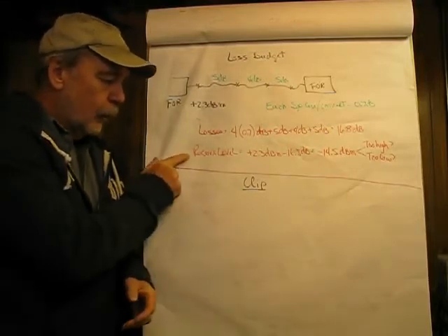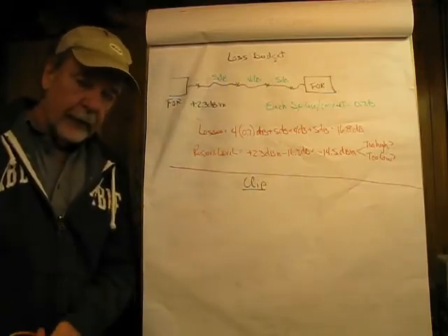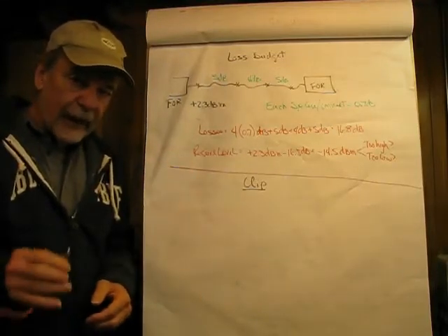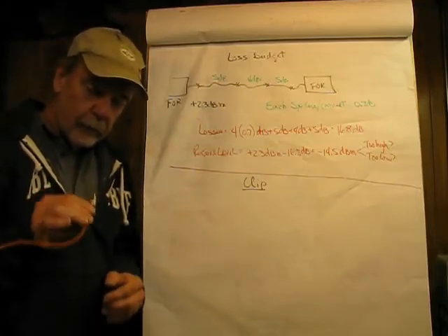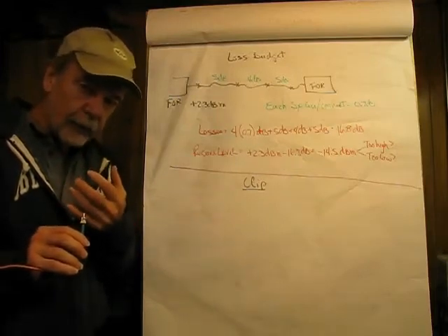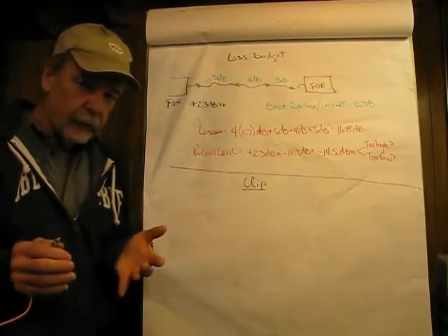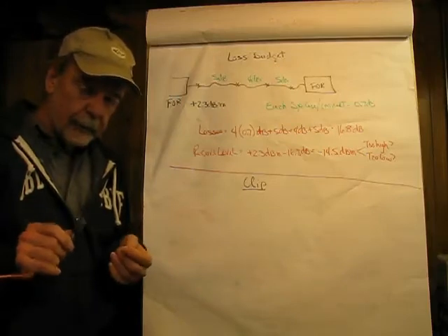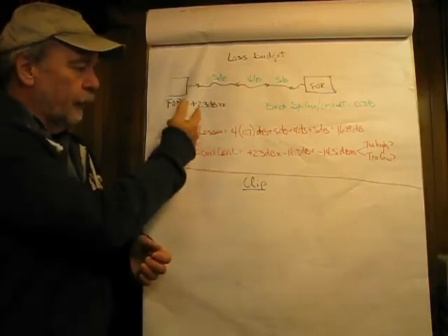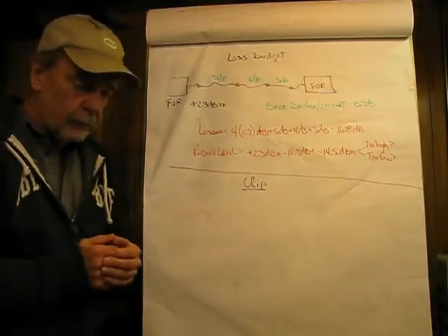Now, high power fiber optic transmitters have devices in them that if you disconnect the cable on the back, it'll turn off the laser. You never, ever want to look into the end of one of these. Bad. It's infrared, you can't see it, you don't know how your lens is focusing it, and you don't want to do any damage to the retina, because it's hard to take an eyeball apart and fix it. Always be careful with this stuff. It's no toy. And the reason, even though this level would be very, very low, if we convert it into watts, is if that's concentrated, it'll melt steel.